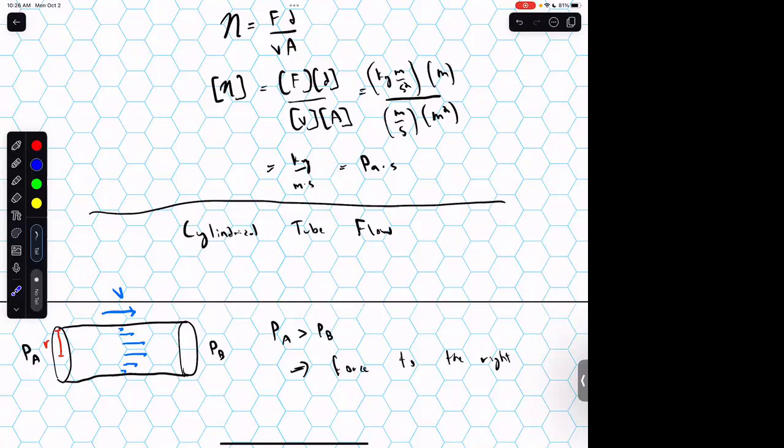What's up? Is there any sort of normal force or friction force along the walls of the container, or is it just moving through inside? So for our purposes, we're going to do an idealized version where the flow doesn't have any components orthogonal, but there is drag force along the wall. That's effectively what causes there to be a lower velocity near the edges. And this assumption that all the flow just moves along the span is called laminar flow, which you might have encountered in other contexts before.